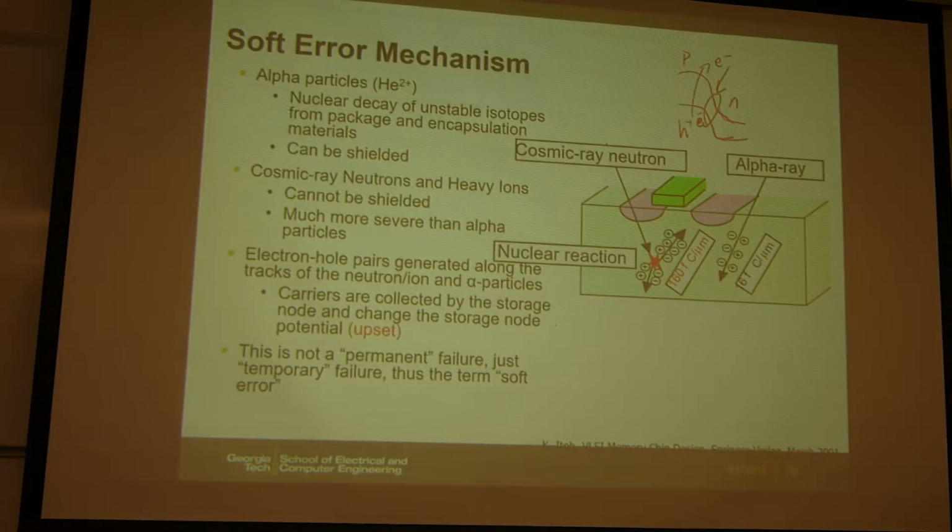So if you create an electron and hole pair, because it's a PN junction, electrons will fall off the barrier and holes will pop up. So basically you separate the electron and hole and you generate a current. Essentially this is what happens when you have the radiation effect in your circuits. The high energy particles hit your PN junction and create electron and hole pairs, and then the electrons and holes are separated due to the internal built-in electric field in the PN junction. So then you create the current.